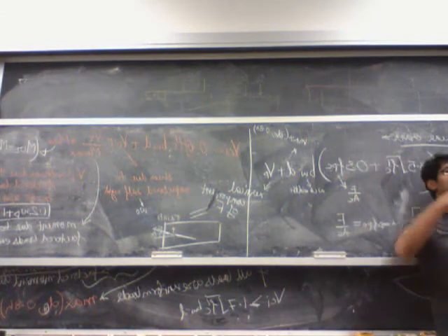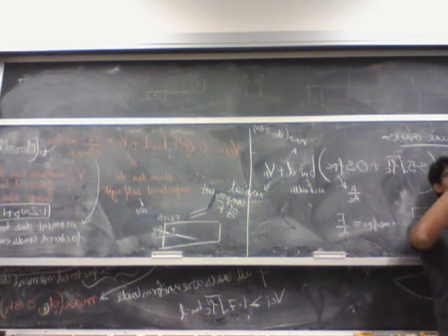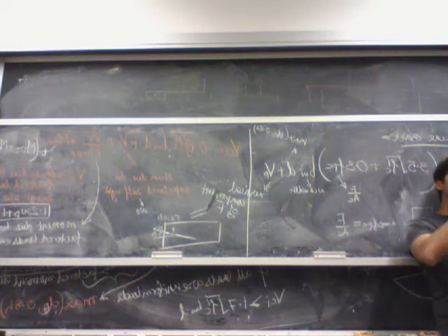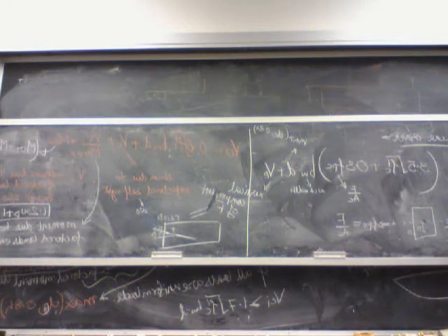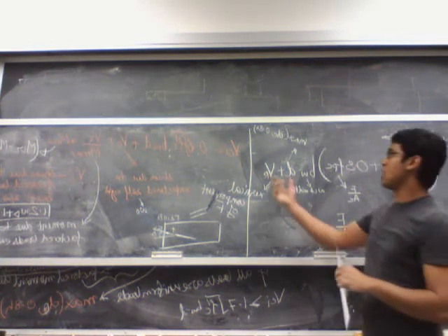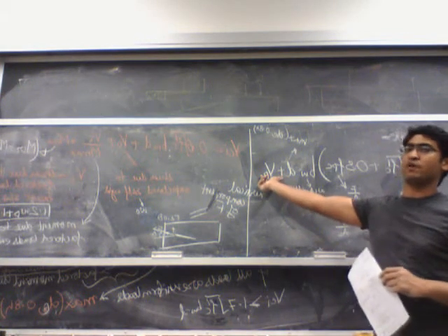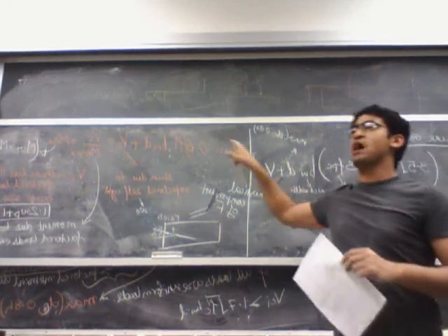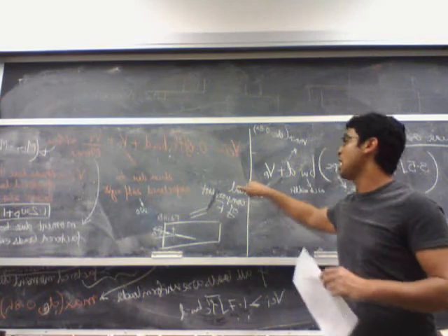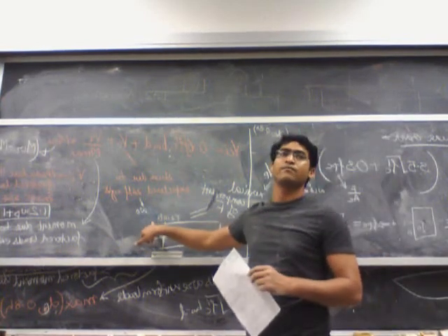So if my tendon is at a certain angle, that vertical component of the tendon is going to resist some of the shear loads. So I account for that vertical component in this term VP. If you have a straight tendon, this becomes 0. If you have an angle to your tendon, then you'll have a non-zero F sine of theta.